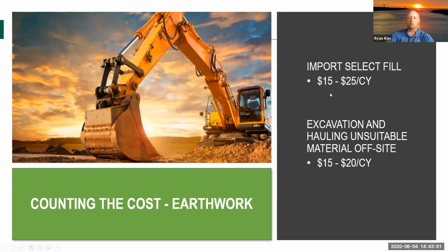As you know, site or construction costs in general fluctuate depending on the project, depending on the time, depending on who your contractor is. So these are just some general rule of thumb numbers that we use in estimating site costs. They go up and down. When it comes to dirt, bringing dirt into a site, a lot of times it's dependent on how close the borrow area is where you're bringing dirt from, and where you are disposing of your dirt. How far away is that? Because that impacts the haul costs for the trucking. So these numbers can fluctuate, but a pretty good idea.